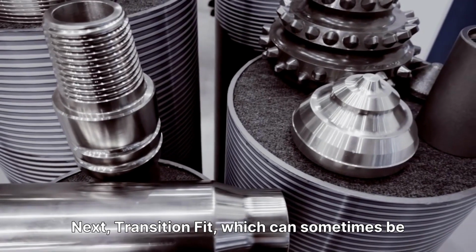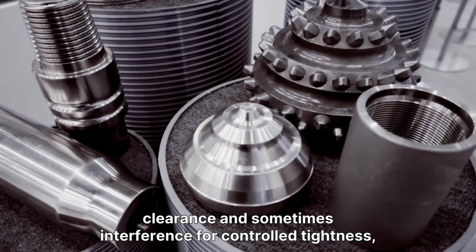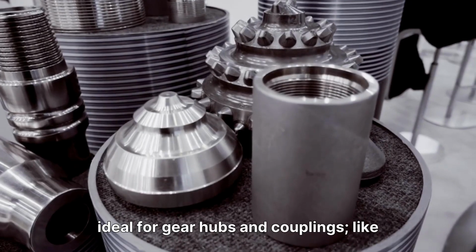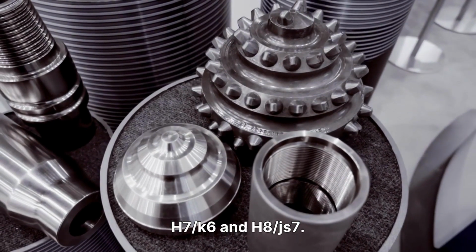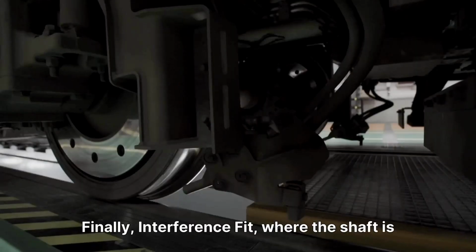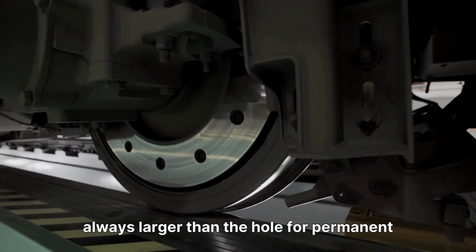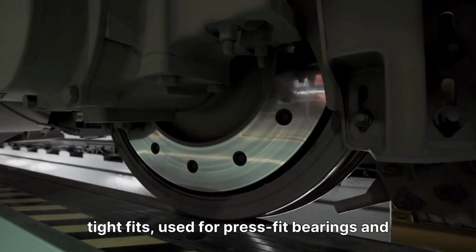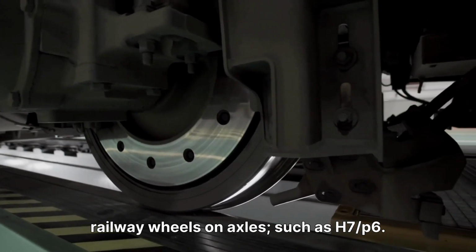Next, transition fit, which can sometimes be clearance and sometimes interference for controlled tightness, ideal for gear hubs and couplings, like H7/K6 and H8/JS7. Finally, interference fit, where the shaft is always larger than the hole for permanent tight fits, used for press-fit bearings and railway wheels on axles, such as H7/P6.